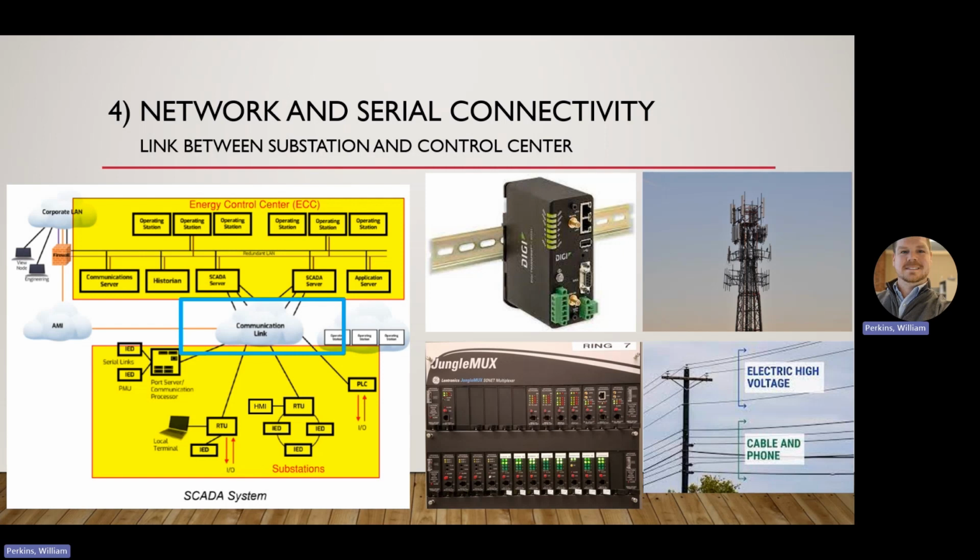That communication medium can either be hardwired via telco circuits, which is a combination of modems and telephone cables, or it could be a fiber network connection with a direct path from the RTU to the ECC, or a fiber ring utilizing multiplexers, which gather all the communications at remote locations and condense these communications onto a single fiber ring, which will route the RTU traffic directly to the ECC and SCADA servers.